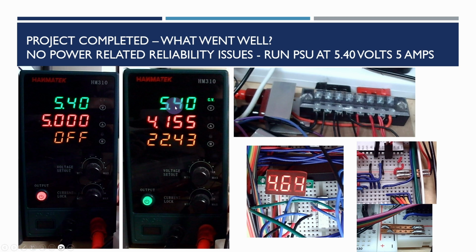Now, I've covered this in the breadboarding tips videos in the past, but making sure that a large breadboard project, so this breadboard project has 25 breadboards in it, you need to make sure that you've got good power distribution. So this is the power distribution block that I showed in the beginning, which actually has wires going out to connectors such as this one here.